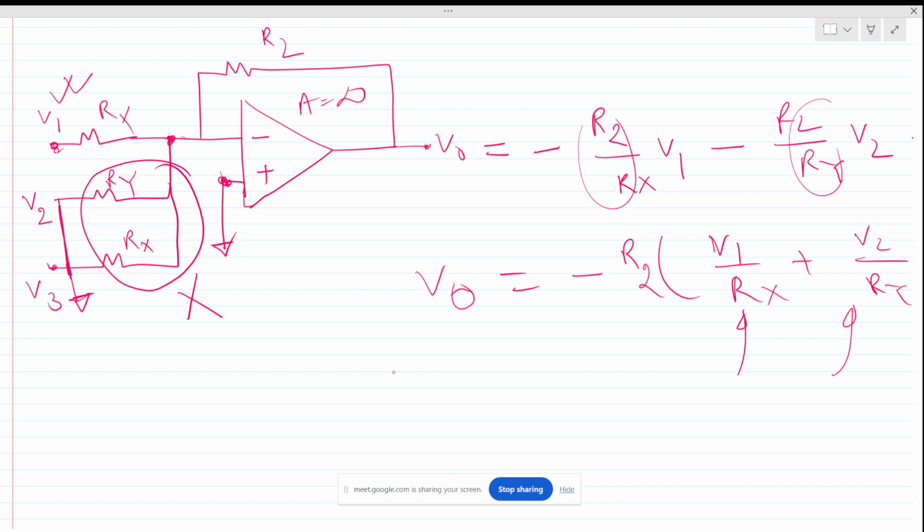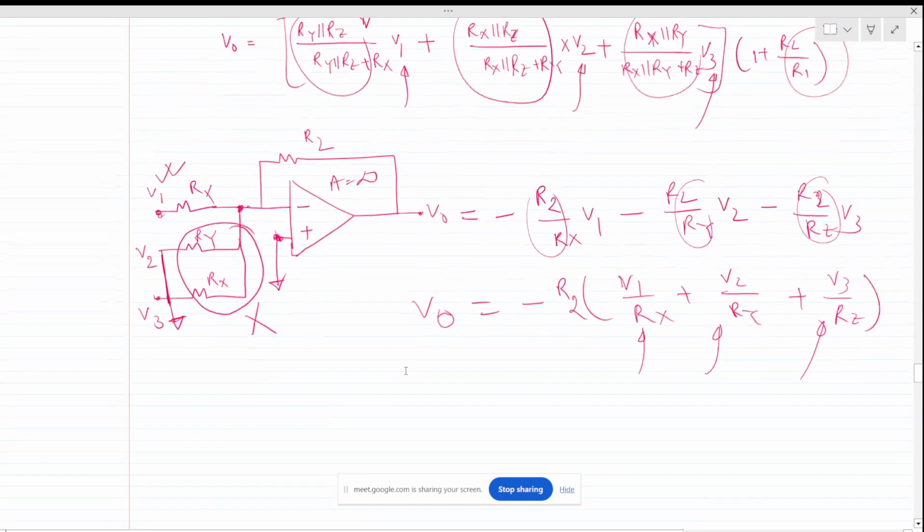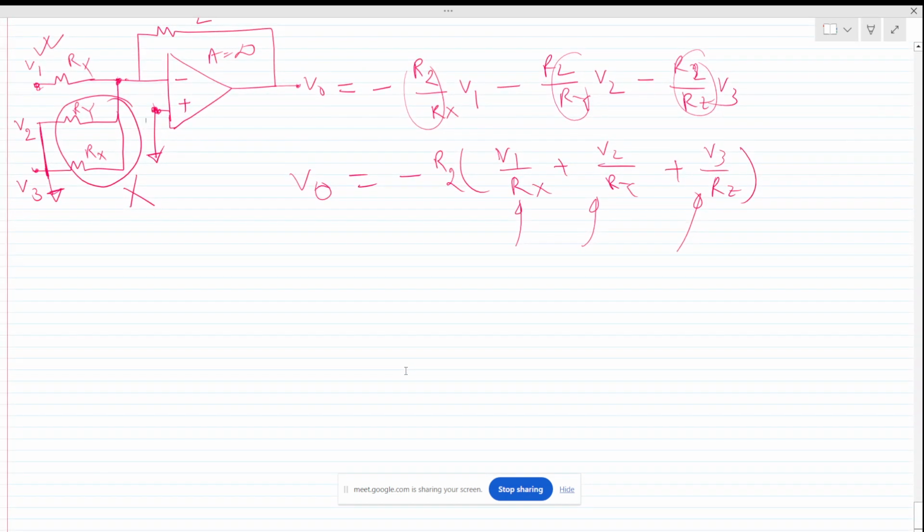If you want to subtract one waveform from another waveform, we can directly apply two different inputs at two different terminals, so it will subtract. Basically an op amp is a subtractor with a high gain, right? Yes, an op amp is a subtractor with a high gain.